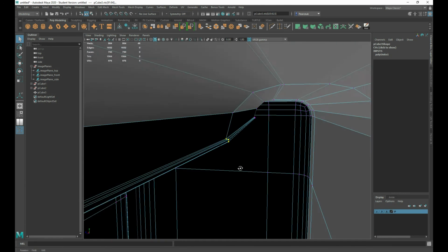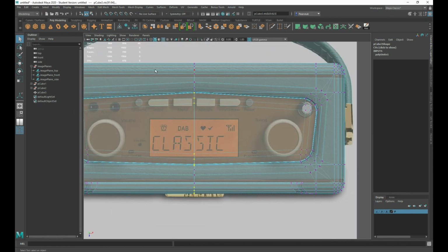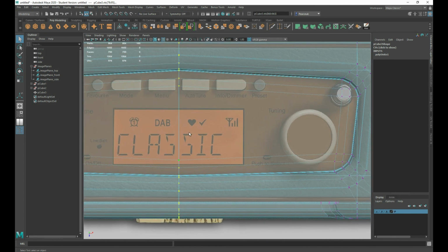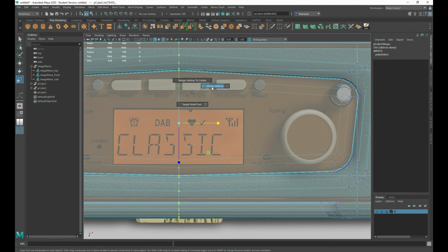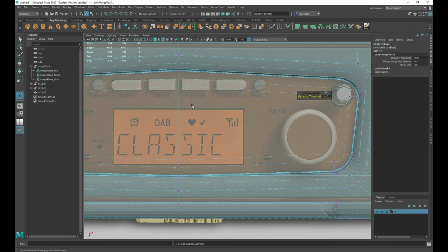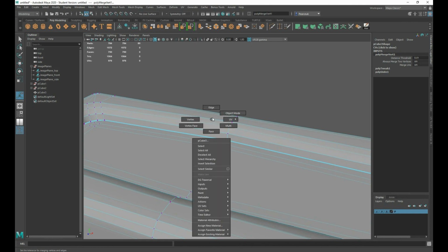So I'm just going to select that middle run. And then I'm going to scale to the middle. And then I'll merge that again. So I would step back a few, so it's at 160 now. And then merge vertice 80. There we go. So now I know that it's halved. It's proper, it's correct.